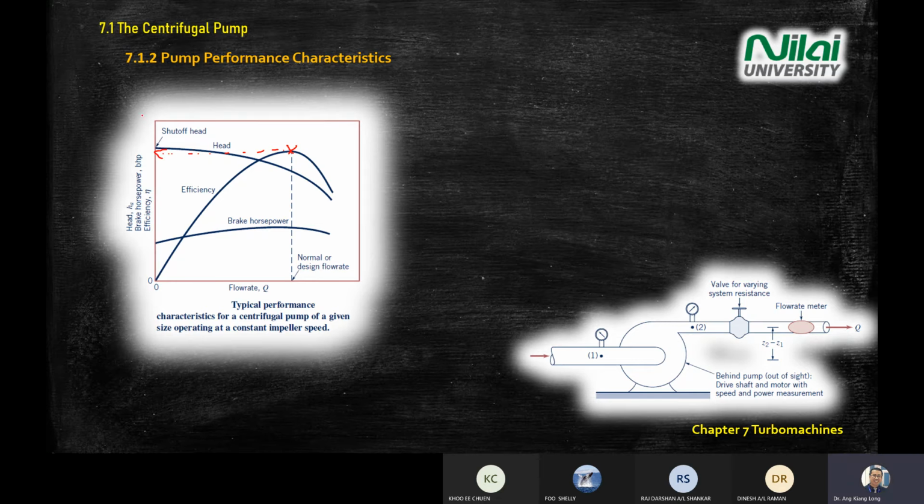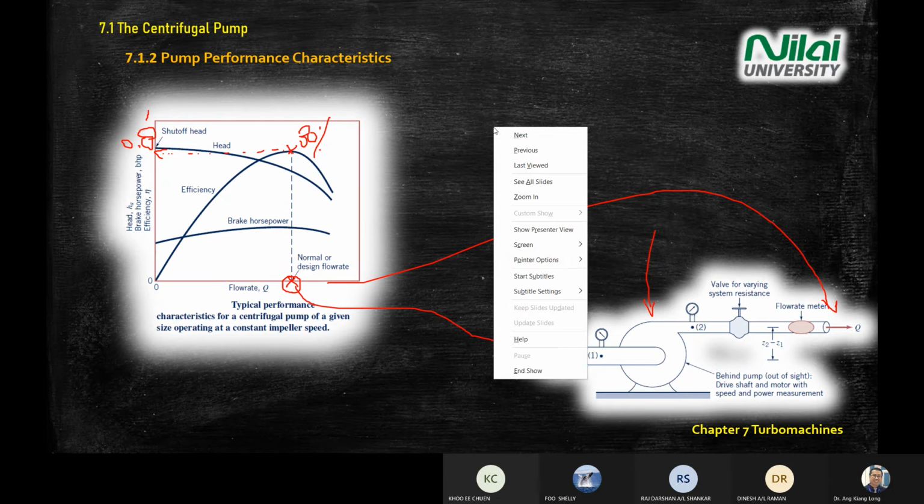So for example, 0 to 1, you know that efficiency maximum is 100%, which is 1. So in this case, I will assume you get around 0.8 something. Okay, 0.8 means 80% efficiency for this pump. And then at the maximum performance of this pump, you project down, you get a value of your Q for your system. Meaning, the maximum Q that you can generate from this pump, you read from this graph. Your Q value at the output is this value. Okay.